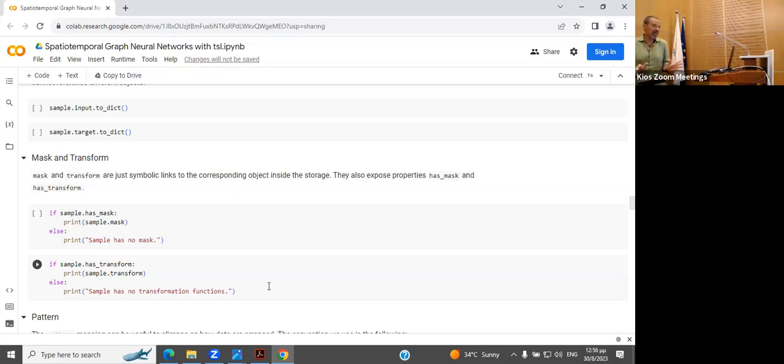I would rather say that if you look at all or most of the physical sensors, not virtual, not those coming from social networks, they are physically dependent. Then we always do what we always do: we try to compensate with respect to the temperature, the humidity, the pressure.